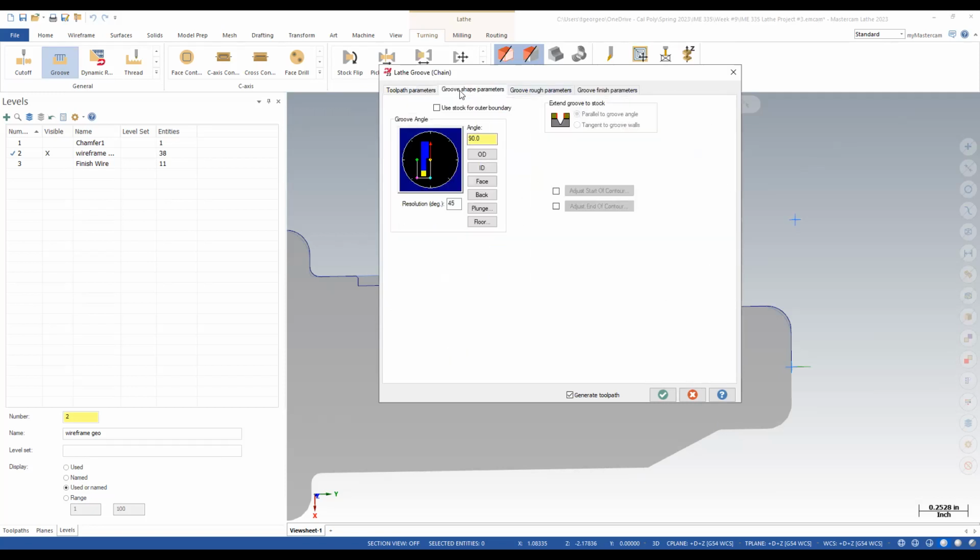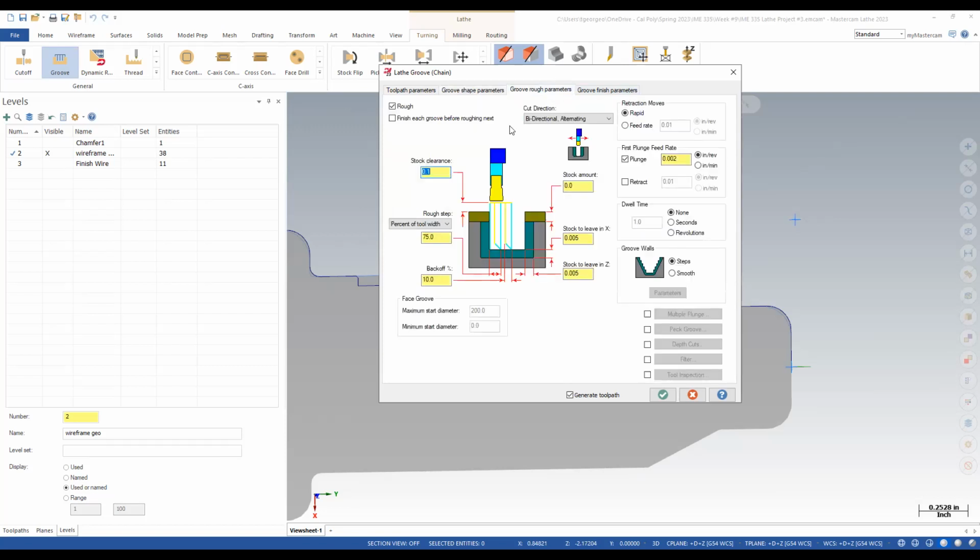this is the easiest toolpath. Groove shape. Do we want to groove in at 90 or any other angle? What do we talk about for roughing a groove at the beginning of the lecture last class? It showed a little insert and it showed you the directions on what we do. What way do we groove in? What way did it groove in the demo? Straight in. What degree is that? 90. Thank you. So in the groove roughing, it's going to come in 90.